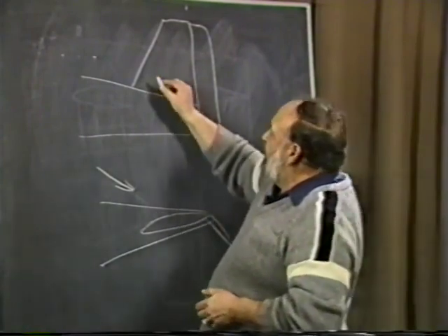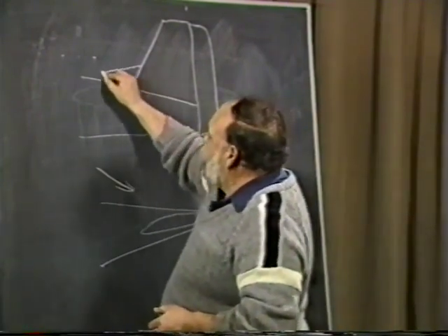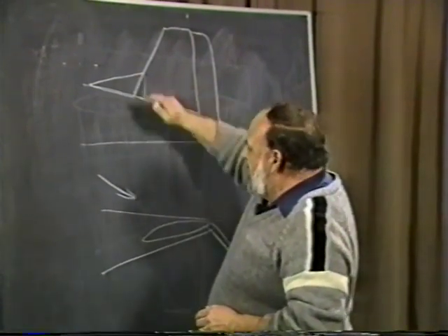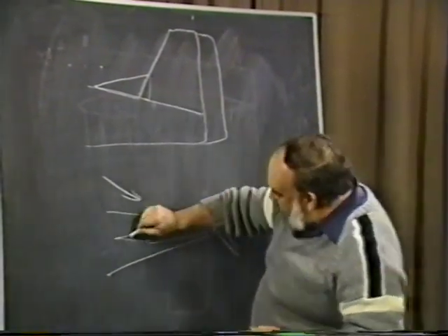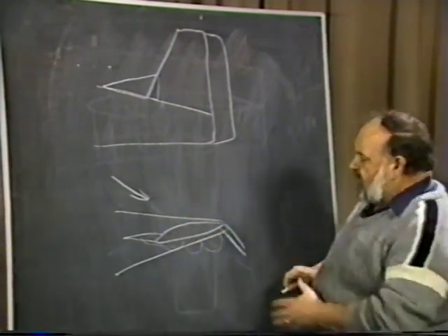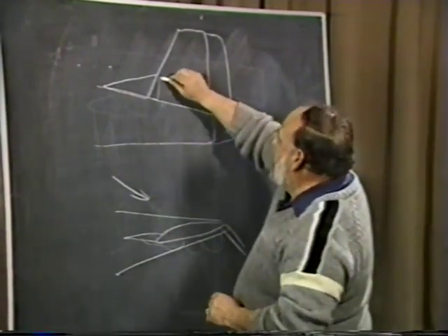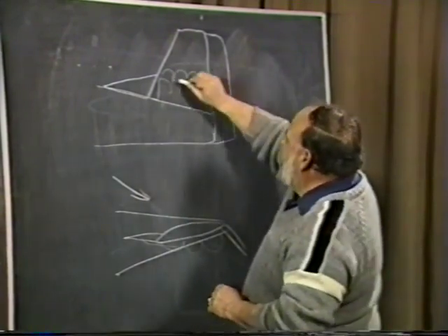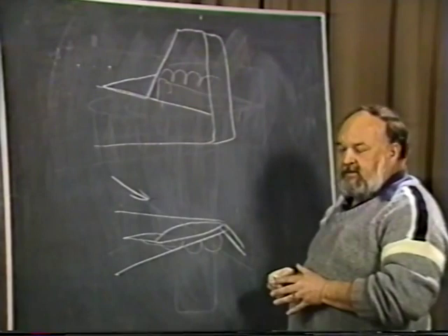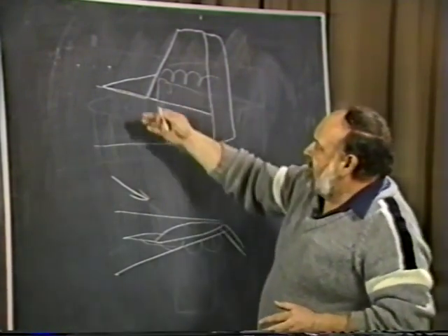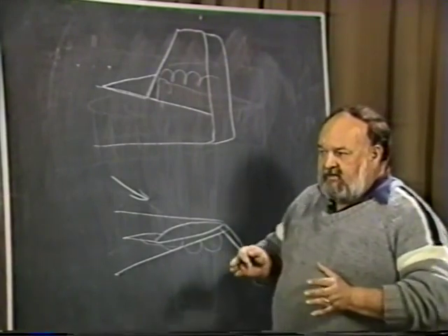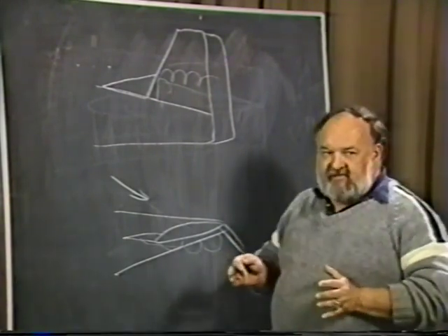One way of solving that, or some of these other little problems, is put a dorsal fin on here. What is this dorsal fin going to do? When you yaw, you have this dorsal fin, it's going to make the vortex sit there and roll around on here, which will keep attached flow. It'll roll right onto here, keep attached flow, and prevent the tail itself from reaching a stalled condition with it. One of the other things the dorsal fin will do, it will give you a nice balance between the directional stability that the fin would be.